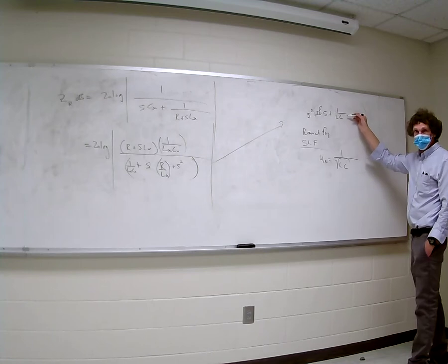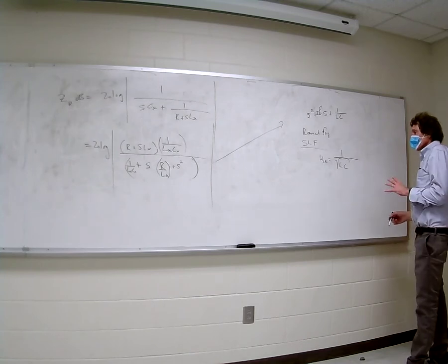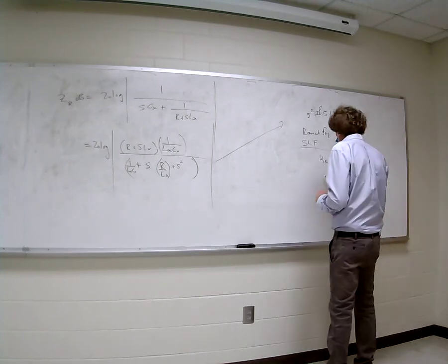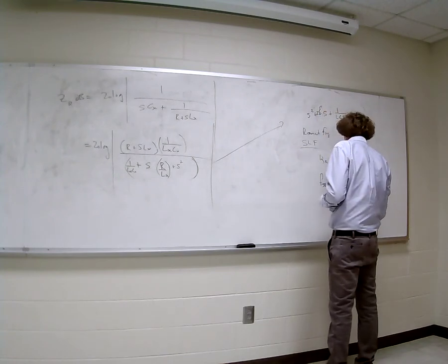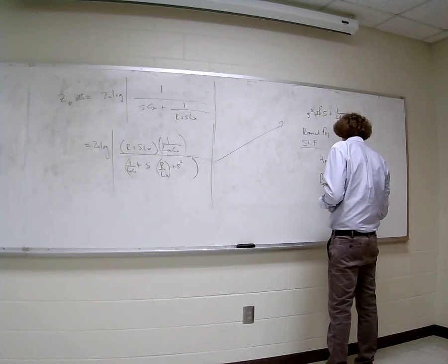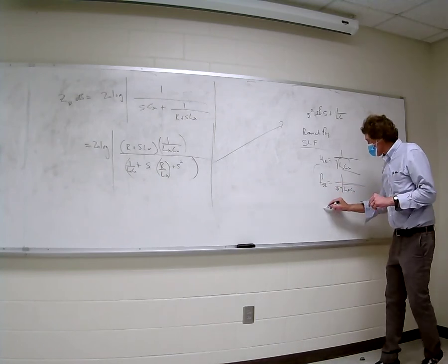Resonant frequency squared. So that's the self-resonant frequency in radians. The one that's probably most commonly shown is f self-resonance, 1 over 2 pi square root of Lx times Cx. This is just saying that I'm getting this now in hertz.